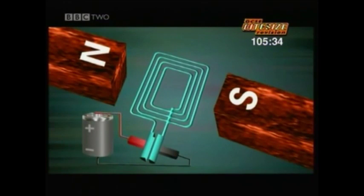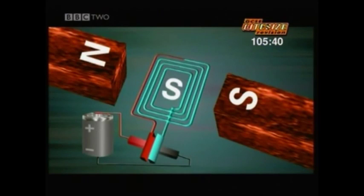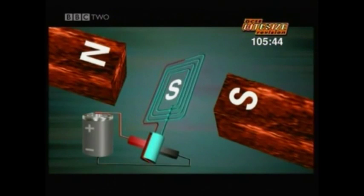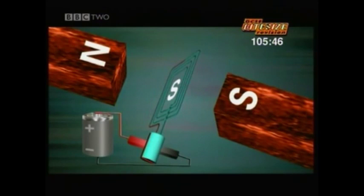Current from the battery turns the coil into an electromagnet. The electromagnet's south pole is attracted towards the north pole of the magnet in the motor casing. So the coil turns round to bring them closer together. If nothing else happened, that would be the end of the story. The coil would just sit still, not going round.